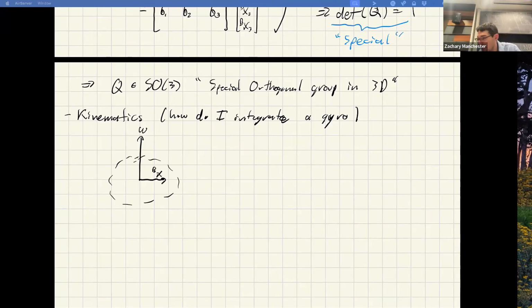So that's the scenario. And now we can write down the vector x in the n frame equals, in this case, Q of t, because it's spinning around so that rotation is changing, times this body frame x, right? That's just definitions. So x_b, the body frame one, I took a marker and drew this on the record. So in the record frame, it's fixed. But in the world frame, it's spinning around, so it's changing. So Q of t is changing, but x_b is not changing.